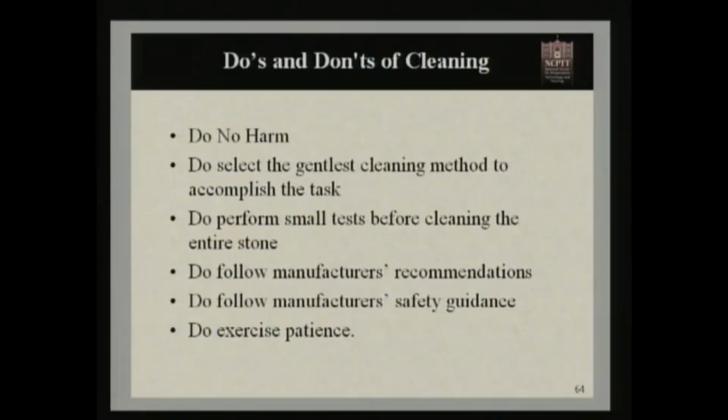Select the gentlest means. You also want to perform small tests, and we'll look at a slide of this in a minute. You also saw a slide of this earlier in Dr. Striegel's talk. Do a small test of different cleaners, especially if you're going to clean a large area in the cemetery or the whole cemetery. You might want to start with a few test patches to decide what cleaner you're going to use on the overall project. We want to follow the manufacturer's recommendations. These are usually on the label. A lot of times you can get them in instruction sheets. We also want to follow the manufacturer's safety guidance, and we'll cover that again in just a couple of slides.